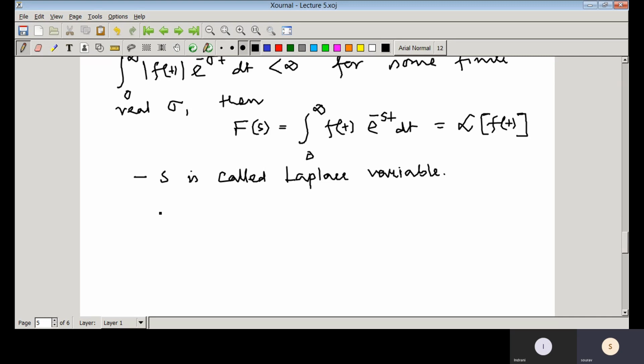One-sided Laplace transform makes sense since the systems are causal, and the integration limit here, you can see, is 0. So basically this is 0 minus. The reason is we take 0 minus to handle the jump discontinuity at the origin.